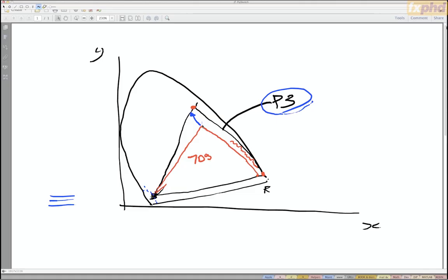Green is supposed to be displayed with these little x, little y chromaticities. That would be colorimetrically correct for 709 green, but if you just plug those numbers into a wide gamut display, you get green, which is wrong. It's too colorful.